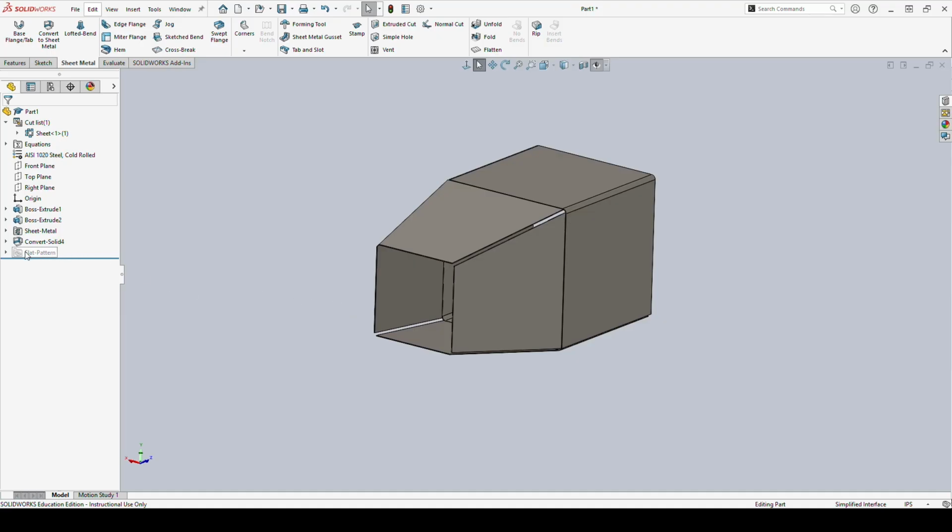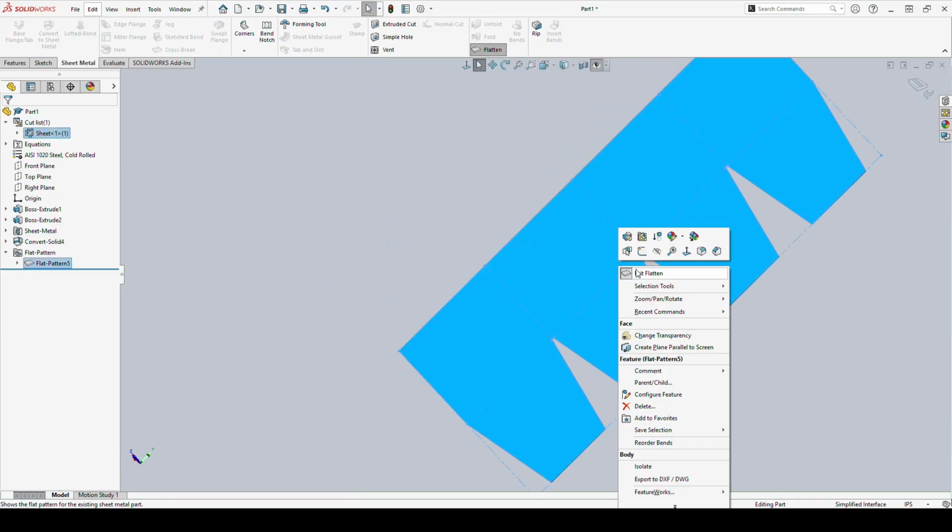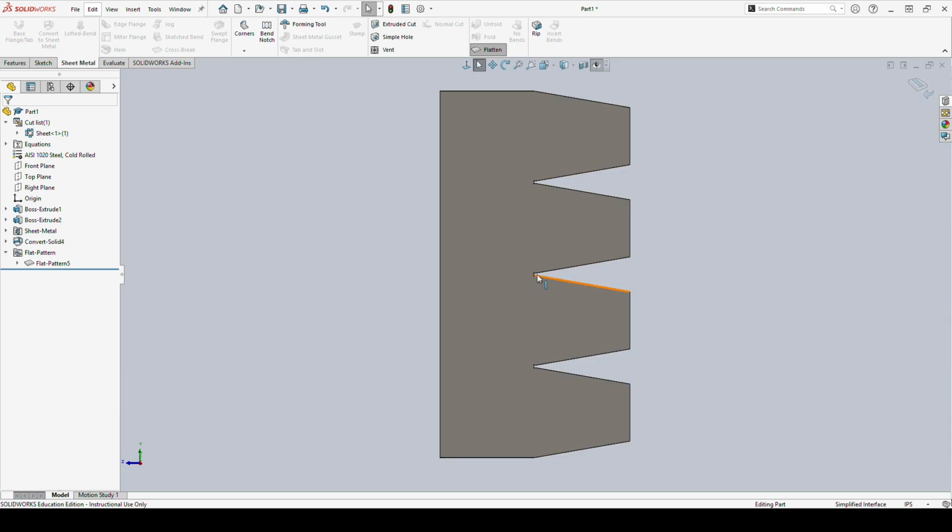That is because this guy actually works, and I'm going to actually use the flat pattern of this guy to show why the other one doesn't work. So looking at this guy, what's happening here is, if you recall before, so now I have the angle. I used extrude, could be a loft, whatever. I had a draft in it such that it came in at an angle. Before, I actually had this set up such that it went out at an angle. So I'm going to overdo that angle a little bit here.